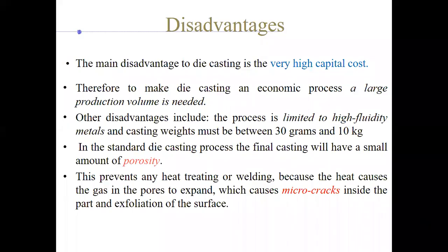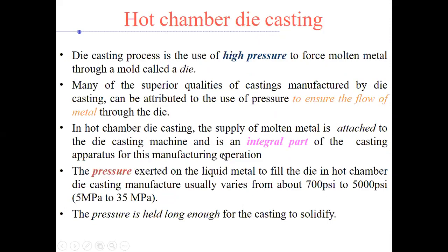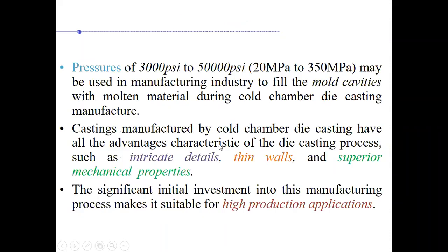So because of that, those pores having gas inside them will expand when subjected to heat. That will cause micro cracks. So that comes off as a disadvantage, you can say, in die casting. Was that clear? Cold chamber die casting.